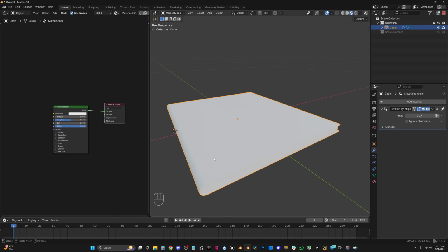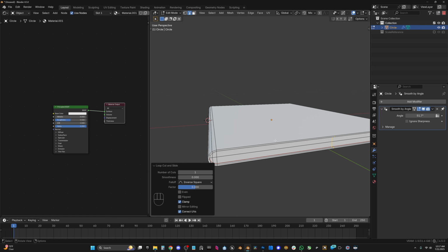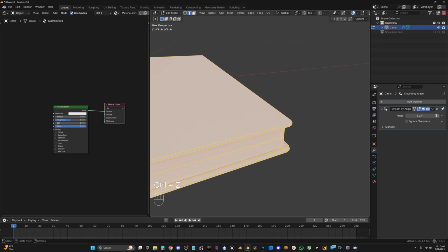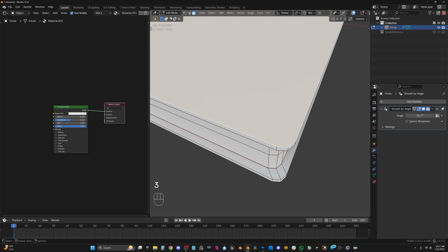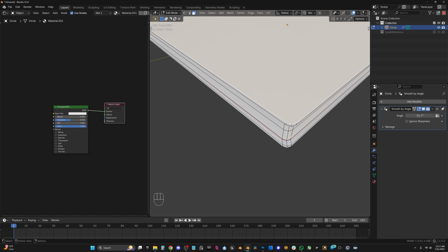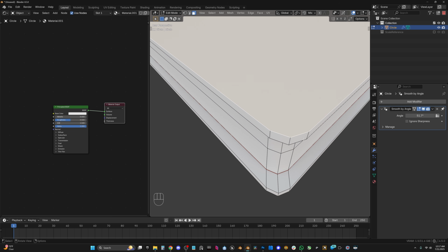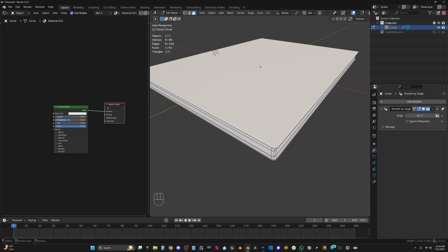Let's do some quick material assignments. I want to have a little bit more geometry. Let me see if I can figure out what's going on here. Yes, okay. So we do not have a quad on the top and bottom cover. And that's because the way we inset this, or the way we bevel these corners, we ended up with 8 vertices. So that's what we call an n-gon. It's more than 4. Really easy fix.